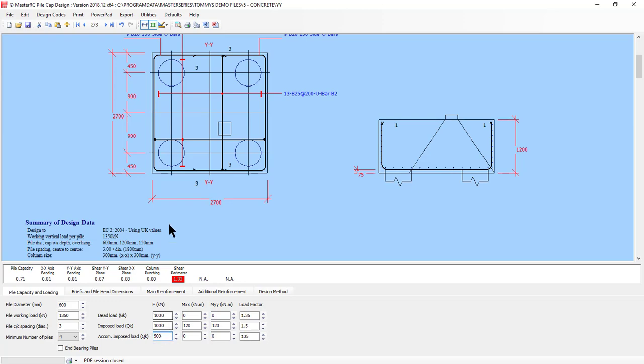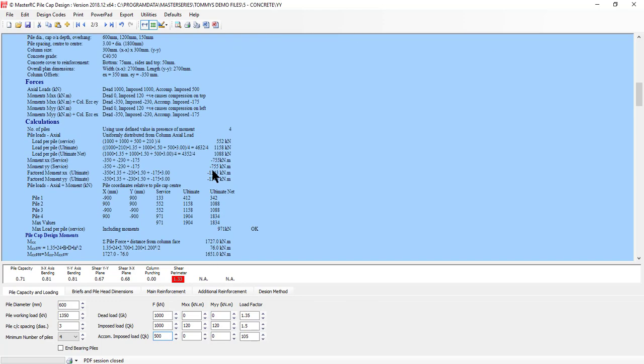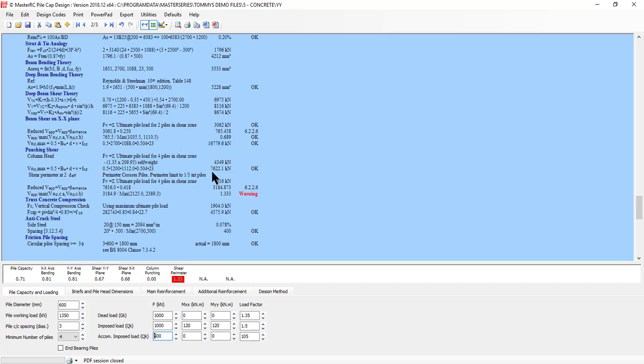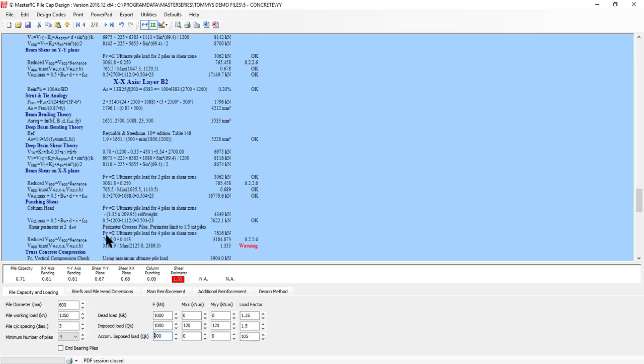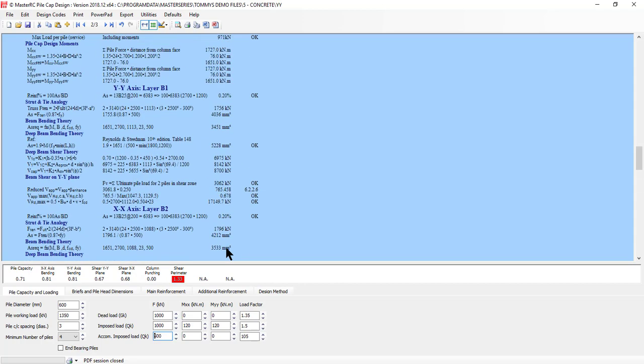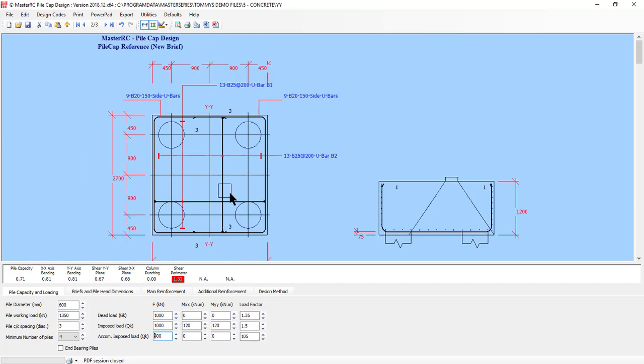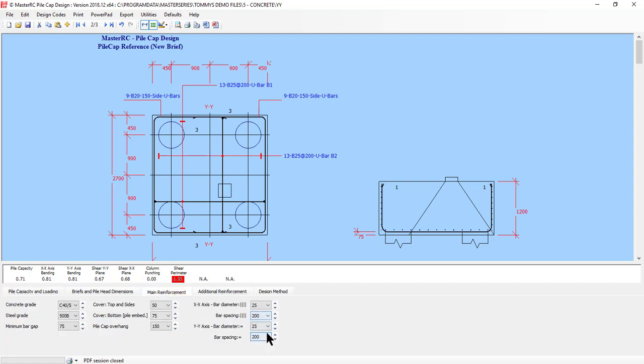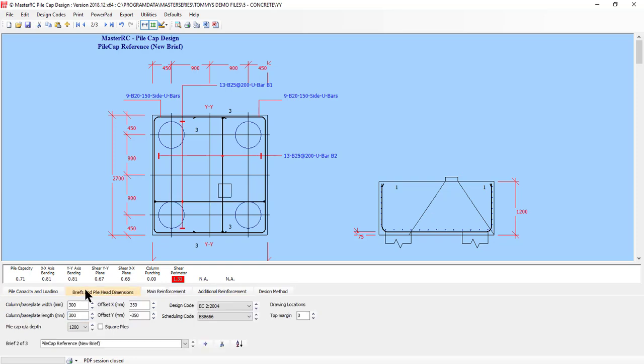So putting in a physical load, you can see now the shear perimeter is unhappy and it's giving us a warning on our shear perimeter. Due to the enhancement, we're at 1.33, 30% overstressing in our shear. So what do we do? Very simply, we can add more rebar in the right axis, which isn't always that beneficial, or we make the foundation deeper.